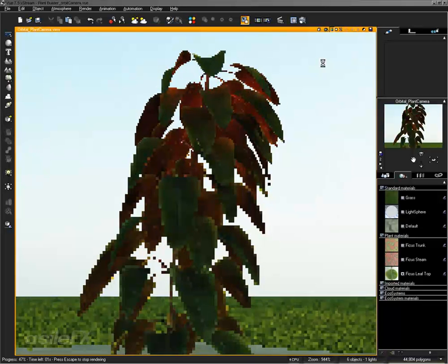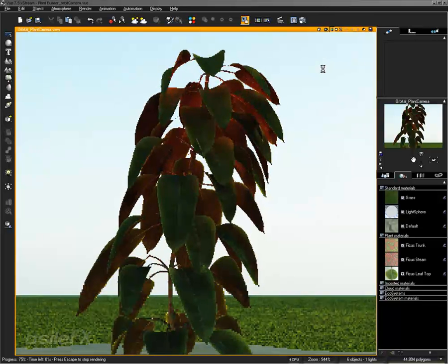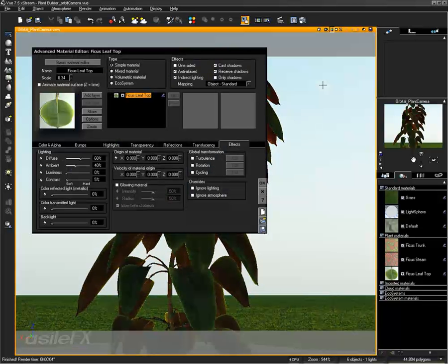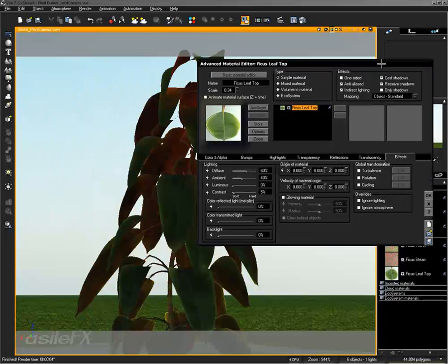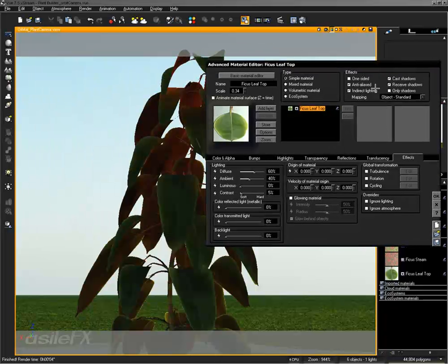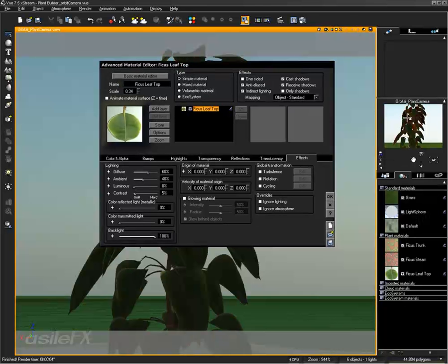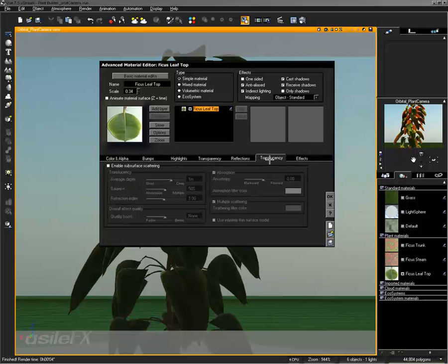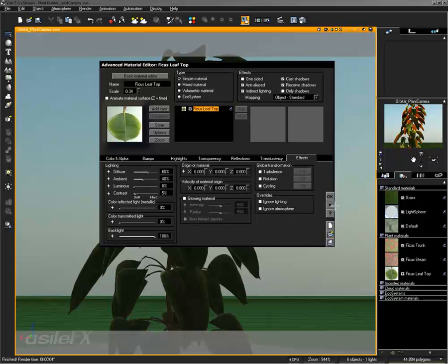If I turn it off, we're only going to see the indirect lighting, so it is still lit up just because I have radiosity turned on. So we do have bounced light coming from the kind of stage object I created underneath. But the backlight, it's sort of a translucency. So instead of actually having to use translucency, we can use the backlight amount and make it glow.